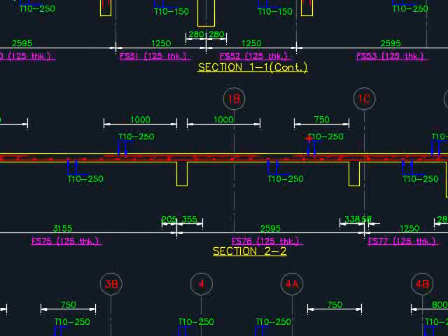Having a little space between the reinforcement bar to save material sometimes is also no guarantee of saving the materials. It is especially so in case of any errors during preparation of the reinforcement bar. It is still possible to have the reinforcement bar being wasted. If they are so closely arranged, you might as well make it continuous. Then the member will become stronger. You feel more confident with the design.